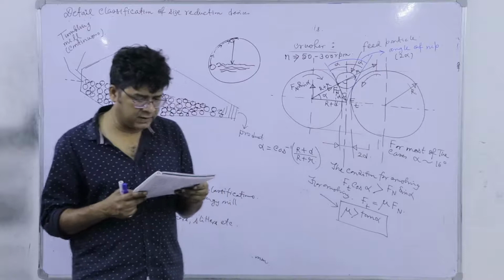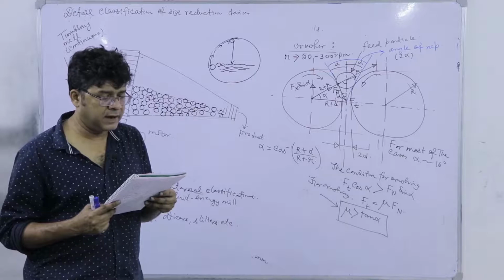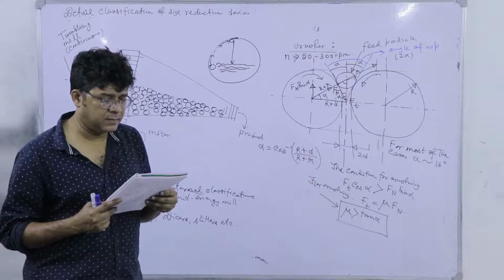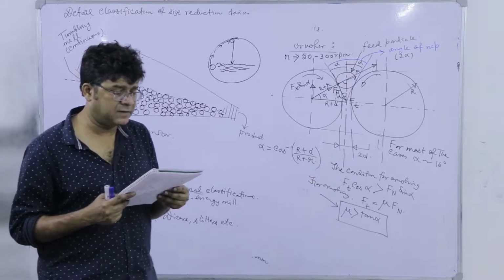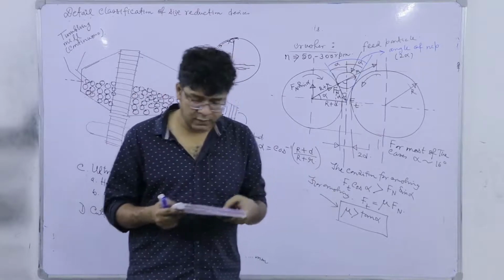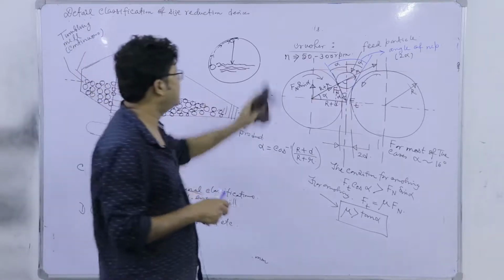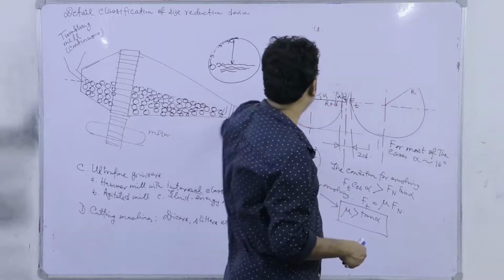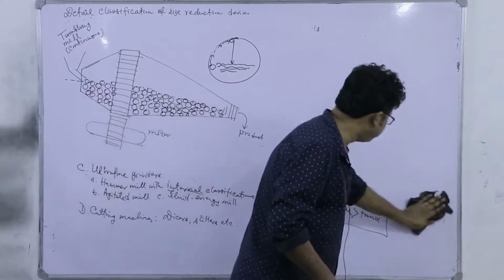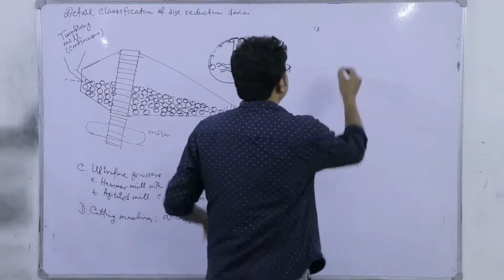And what type of balls do we use? We can use metal, then zirconium balls. For intermediate and fine reduction of abrasive materials, tumbling mills are used. What is more important than this description is that we have to calculate the critical speed. Because if we know the speed limit, I can operate at 50 to 80% of that speed.